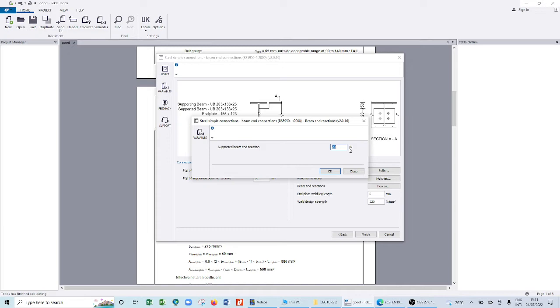0.94. Some people like following more of the detail, when you check whether the slab is two-way or one-way slab, then after that the load is distributed in this format. But to be safe, if you have to go through all this, time may not allow. So what you do is just take it will take a half, then it will take a half like that. So then you have half of this, and half of this only,